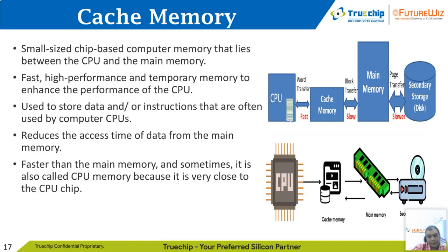The CPU first talks to the cache, and the controllers around the cache will bring data in from main memory into cache, because access to the main memory, which is the primary memory, is typically slow compared to the requirement of the CPU. So the cache is somewhere the processor and the other controllers will try to bring the data into for fast access by the processor.